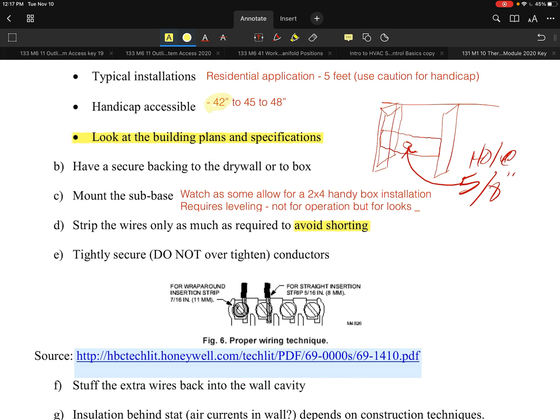The thing I want to point out is that you don't want a ton of extra conductor just hanging out in the middle. You want most of your conductor covered by the screw or in that particular area. Any additional, you're just risking a short, or having something burn up or smoke a transformer, or thermostat, you name it. So you want to be careful on that.